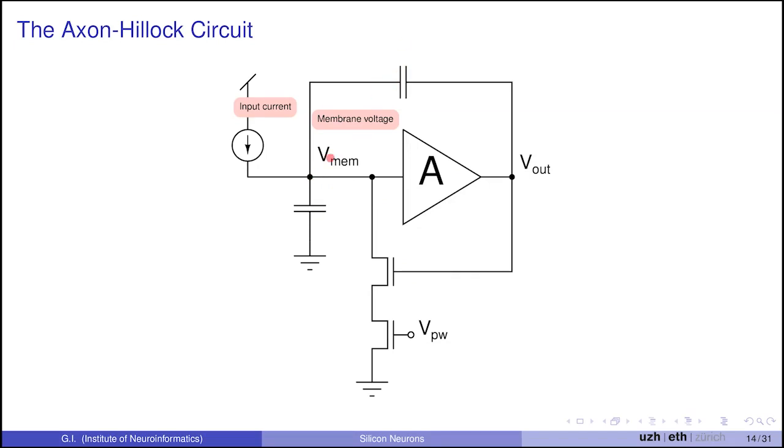Actually, it goes into this parallel capacitance arrangement. And so Vmem starts to increase linearly because it sees these capacitors. So we have C dV/dt. If we have constant input current, we have a linear increase in Vmem.